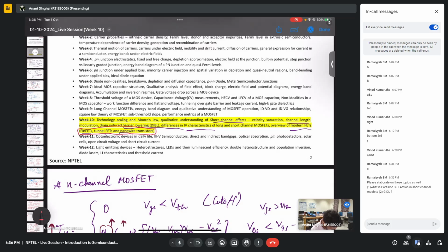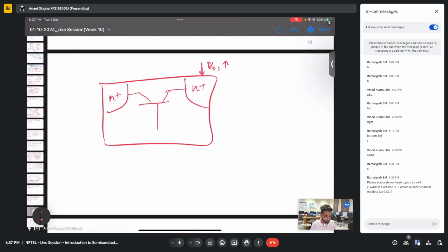So in a MOSFET, which is N plus, we need to go very deep for this. Once we have a very large VDS, we have impact ionization. As we apply higher and higher VDS, we have generation of holes here. Let's say I have applied a very large VDS, a positive voltage. The electrons go like this, and a very large body current comes into the picture, because the body is basically holes, right? These holes will move from the drain to the body.